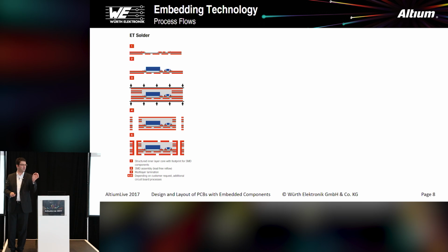Those are just some small frames in the area where you really need the functionality of the solder resist. And the solder surface is something like tin or whatever, not gold, because gold won't combine with the resin from the printed circuit board later on when you do the lamination. So you need a solder surface which also acts as an adhesion promoter for the lamination afterwards.